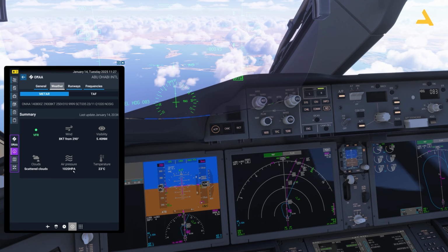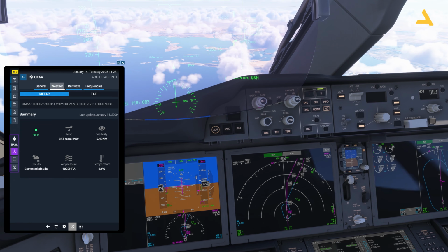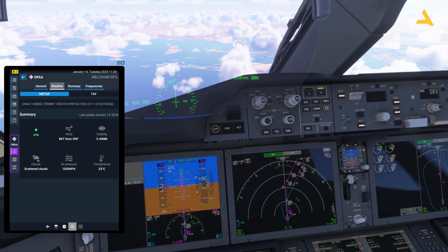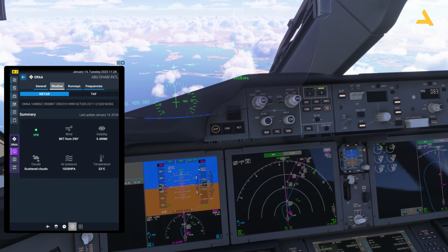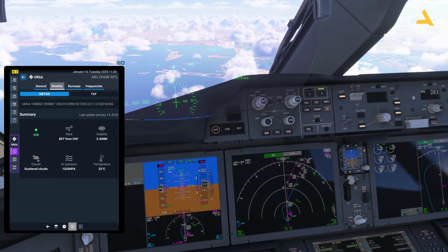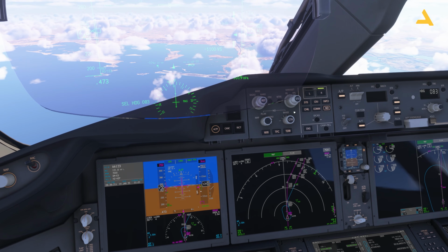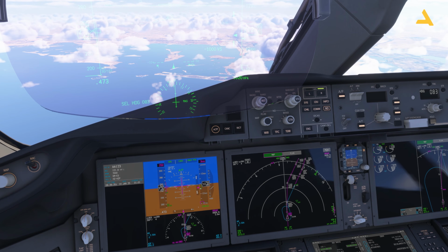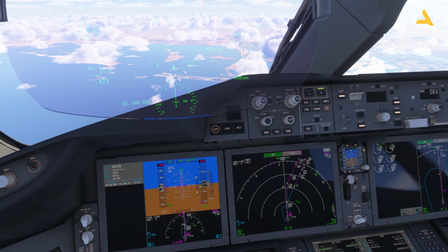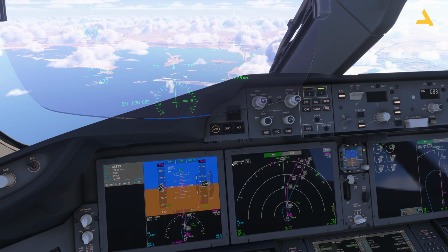Weather 1020. So I can now press this button, standard, and change the units, and I can move this knob, the smaller one, to change the barometric pressure. Otherwise, I'll just show you one more thing. If you press comma on your keyboard, it will be adjusted. It's 1019. So I can just keep it like this. Or if you want, you can change it to 1020. You actually have to do this in order to get the correct readings for the altitude. So if you're getting this by pressing comma, then just keep it over here.